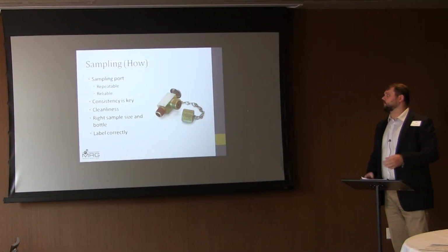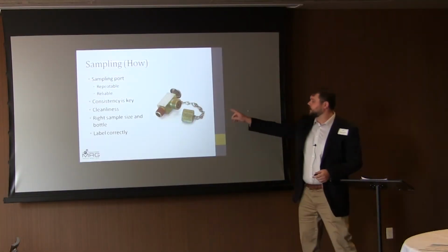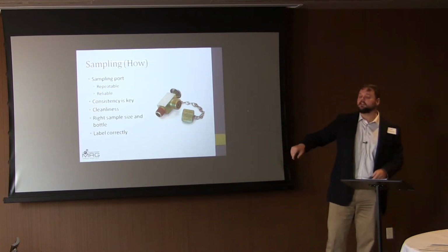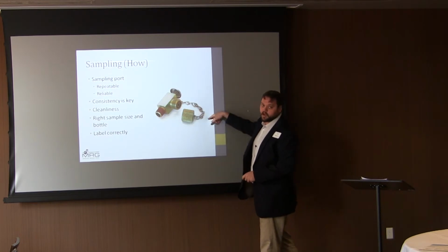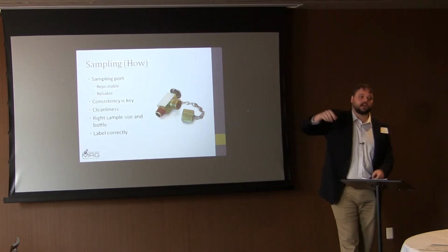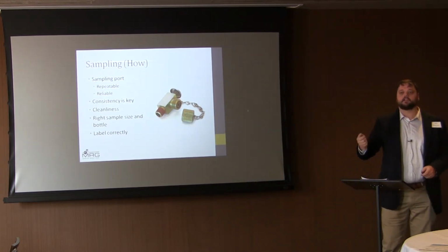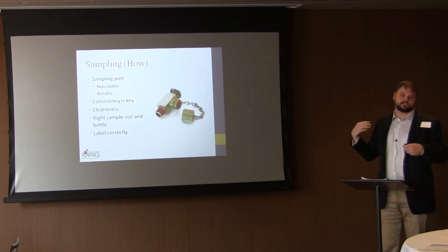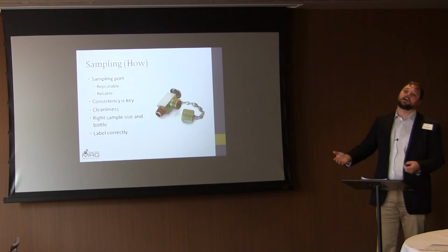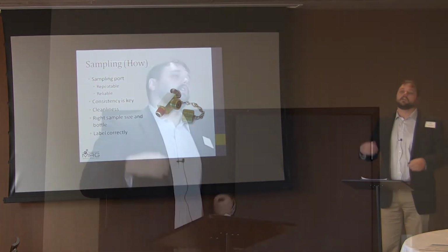And more about how. This is also another setup that can be retrofitted onto a machine, and then you would come along and hook up a tube and a bottle, and then you just unthread that. Oil would start flowing out. You take your sample, close it again. So the same idea is you're also minimizing risk for your equipment because you're not opening up your equipment. You're not opening the chance of the dust to get in your equipment, hurt your equipment, vice versa, hurting the sample.